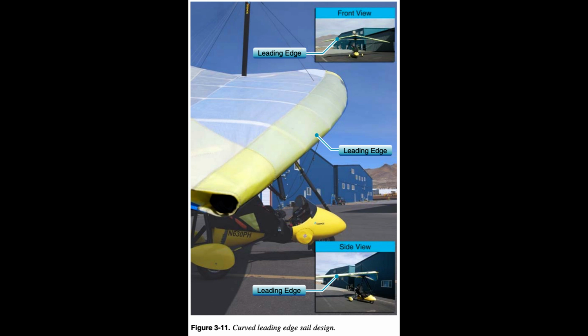Sail material and panels. Sail material is a combination of polyester materials designed with different weaves, thickness, and orientation to fit the design mission of the wing. Panels are cut to different shapes and laid down at different angles to provide the stiffness and flexibility where needed for the specific wing design. Automated machines typically cut the fabric to precision tolerances and the panels are sewn together with high-strength thread.